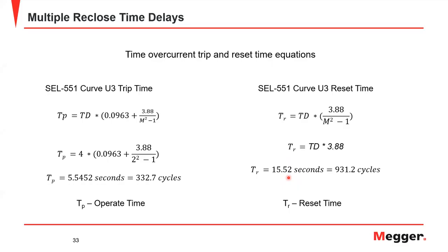The reset time is very slow, and if you've ever seen an induction disk relay work, you'll understand that you can reach up and use your finger or the eraser on a pencil and reset it faster than you can wait on it to do it yourself. Okay.